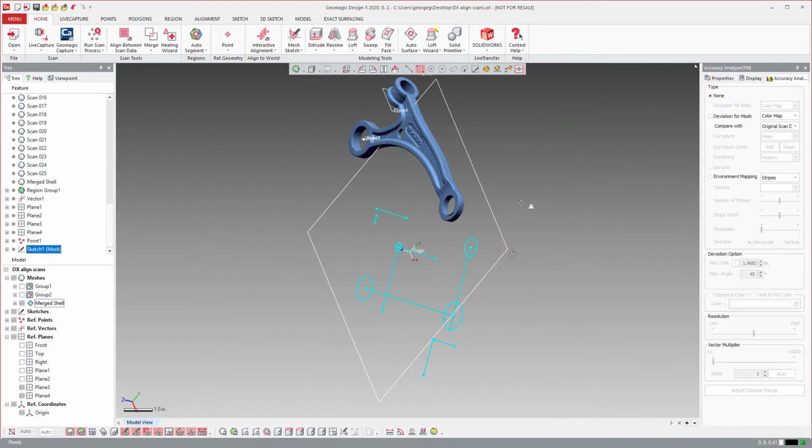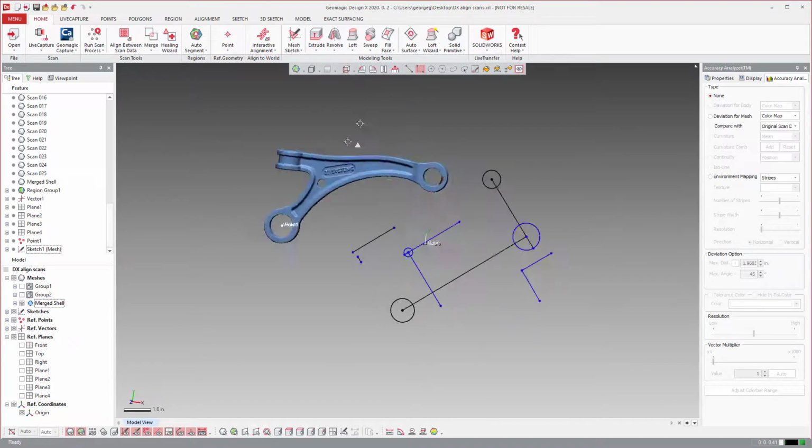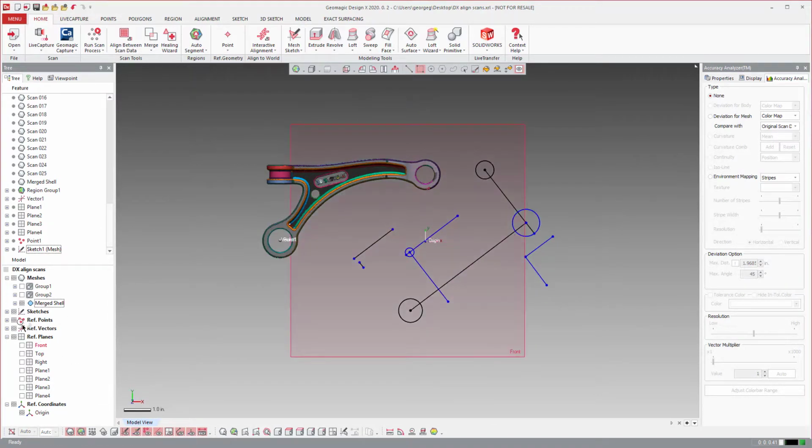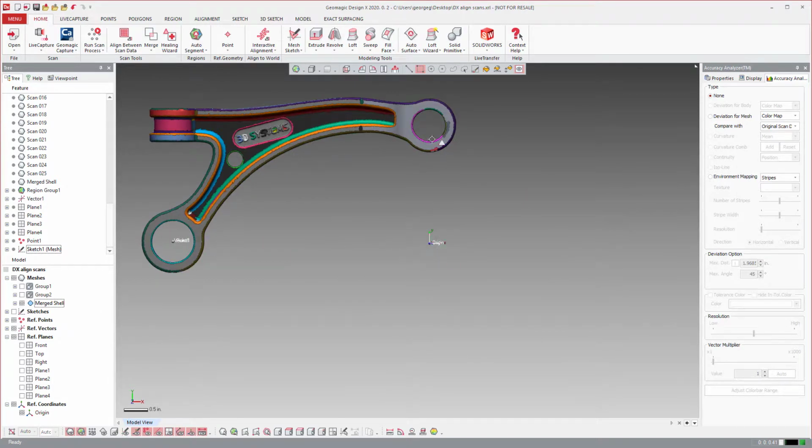Now when I hit OK, the sketch does not move. That's one of the little caveats with this, is the sketch doesn't go with it, but it doesn't matter because the part is now in that coordinate system. And I'll go ahead and hide my sketches, and 0 is at the intersection of these two, but squared to the edge of that and the edge of that. So I could have easily used squaring it to the cylinder axis and squaring it to that top plane if I wanted to.